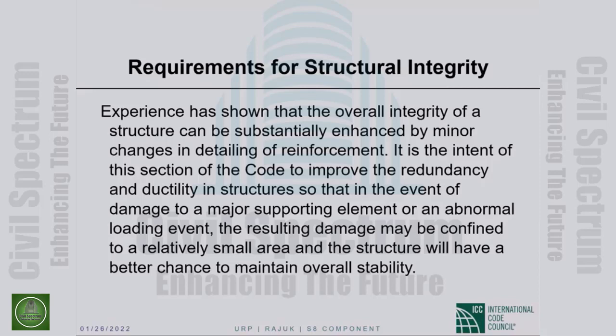In the best of circumstances, it can be a compression lap splice. You remember the discussion. If you look at the picture that I showed you, the dowel has to lap with the lower column bar and has to lap with the upper column bar. And the lap lengths have to be sufficient; look at the example that we went over yesterday, column bar splices. So that's what you will have to provide.